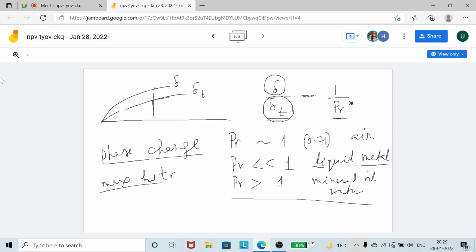Or steam in a power plant, that also takes up the heat. And for very high transfer, it should take the latent heat HFG. So there is phase change also involved. So what we are learning, that heat transfer increases if you move from natural to forced, gas to liquid, and go to phase change. So maximum heat transfer you go for when you do phase change.